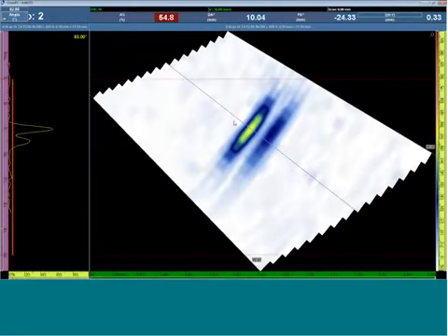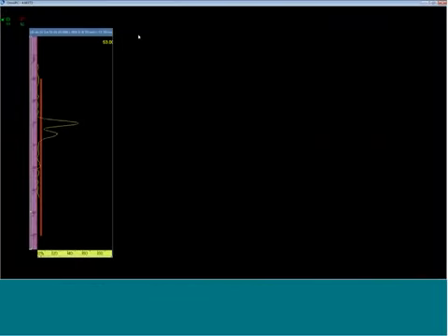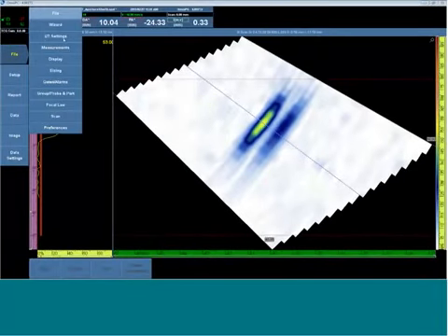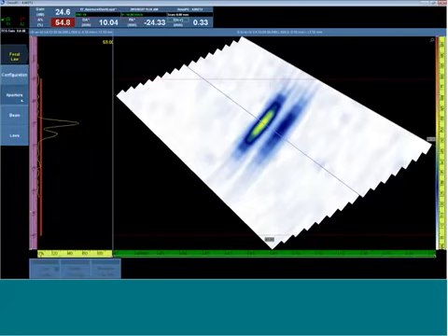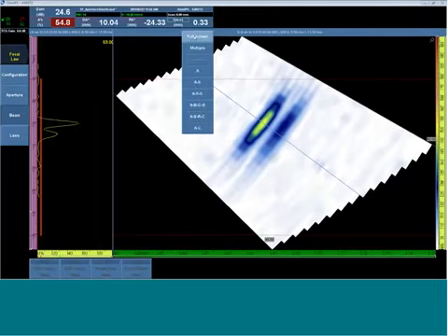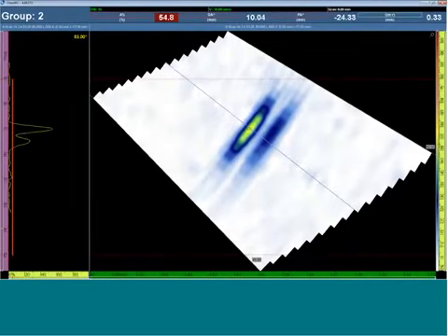With a 16 element focal law aperture, focused at the depth and a 1 degree step, we can see our ability to measure the center of this tip is compromised.